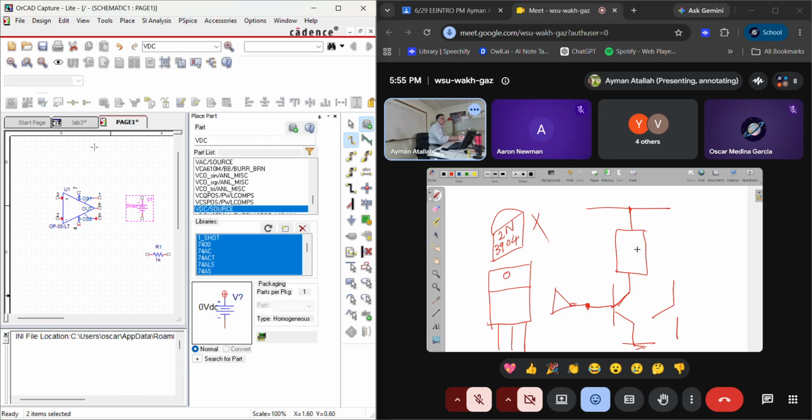The operational amplifier only controls the on and off, turning the motor on or off through this switch. The power doesn't directly come from the operational amplifier, because its current is too low; it is used only to turn the switch on and off. The motor gets power from the DC power supply.